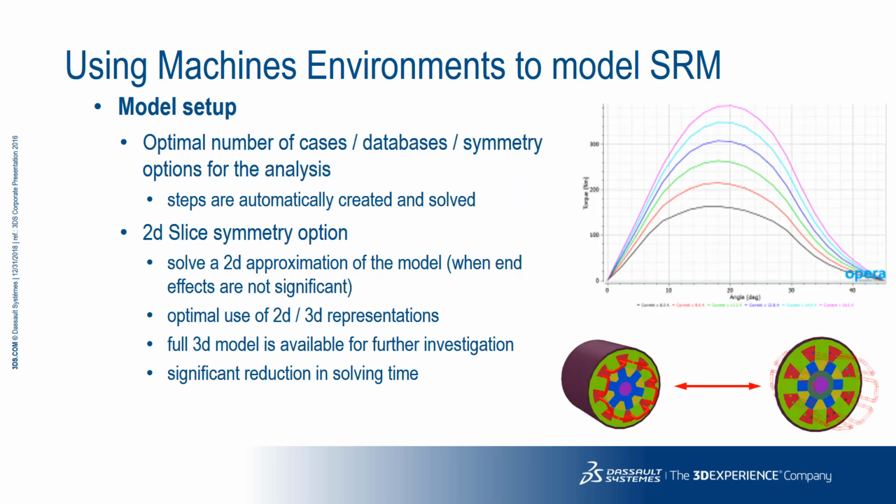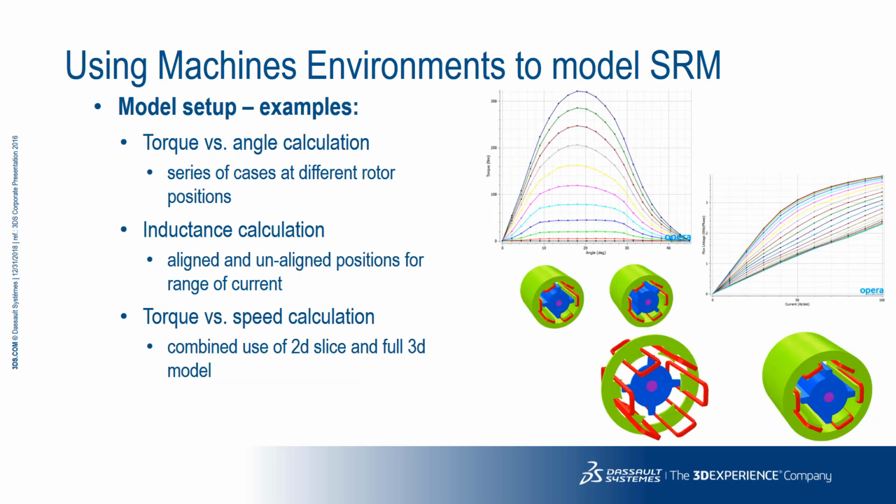Depending on the assessment that you wish to carry out, the machine's environment will create the optimal number of cases to solve. Since the environment can be used at the conceptual design stage, the user also has the choice of running a single element thick slice of the model rather than the full 3D. This will speed up the analysis time enormously and allow the user to home in on initial designs before verifying the results with the full 3D model.